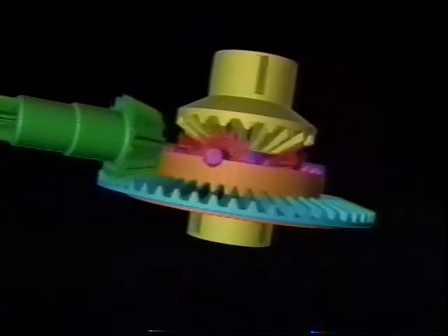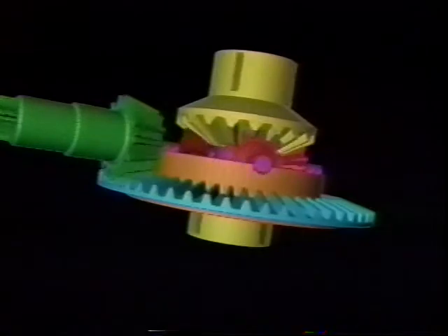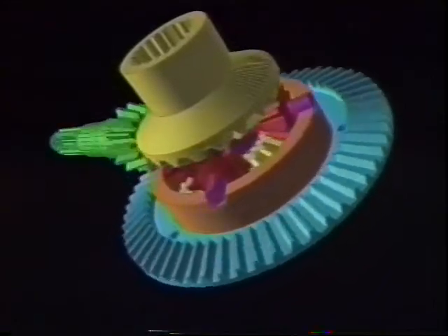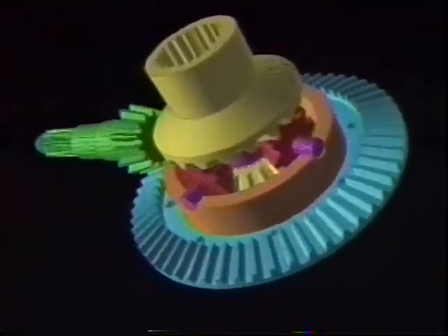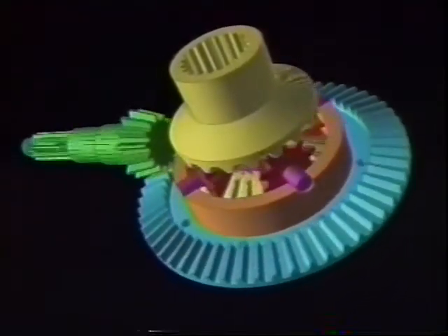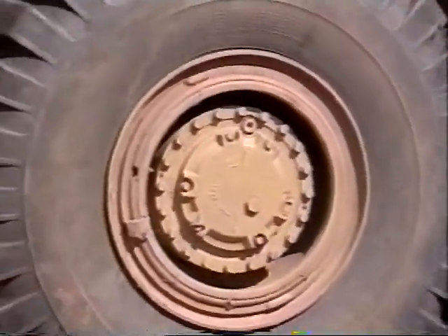The standard differential is good for many situations, but if a vehicle equipped with a standard differential loses traction on one wheel, the slipping wheel triggers differential action, sending available power to the slipping wheel where it is not needed. This takes power away from the non-slipping wheel. To avoid slipping wheels, some off-road vehicles require a differential that is a bit more complicated.